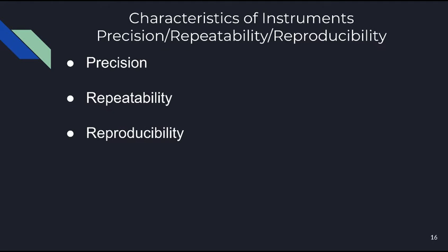Precision is a term that describes an instrument's degree of freedom from random errors. If a large number of readings are taken of the same quantity by a high precision instrument, then the spread of readings will be very small. Precision is often, though incorrectly, confused with accuracy. High precision does not imply anything about measurement accuracy. A high precision instrument may have a low accuracy. Low accuracy measurements from a high precision instrument are normally caused by a bias in the measurement, which is removable by recalibration. The terms repeatability and